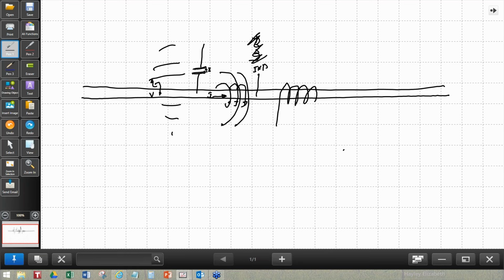Capacitance typically will be to infinity, although you can talk about it being back and forth on the same wire. The inductance is typically per unit length in the wire. Both store energy, both exist. Hence, there is a characteristic impedance that this wire has. And that's important to know because that's what you have to match if you want to send energy down this wire.